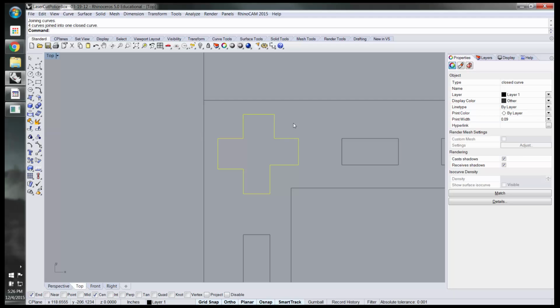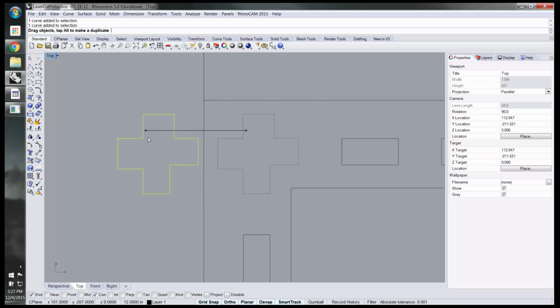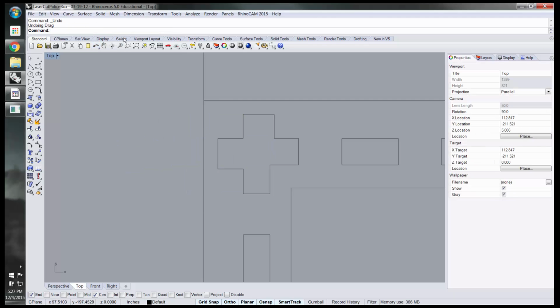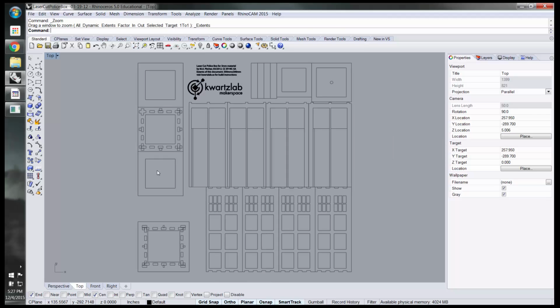And then we need to go back and join those, which will make the laser cut it even faster. So anytime we have a shape like this, we want to make sure we've joined it. We make sure there are no lines that we don't need to cut. There are no overlapping lines, even to the point of grabbing it and moving it to make sure there was nothing underneath of it. Those little kinds of tricks really make a difference with this.